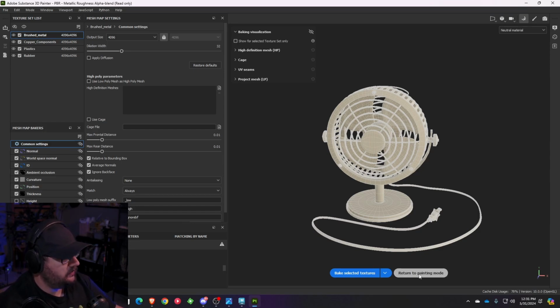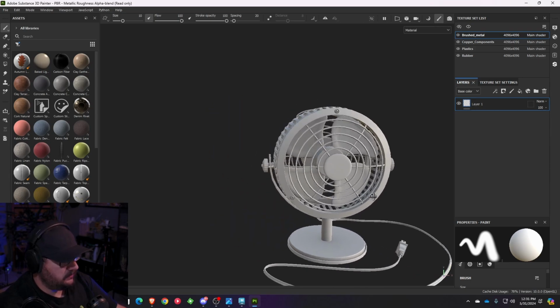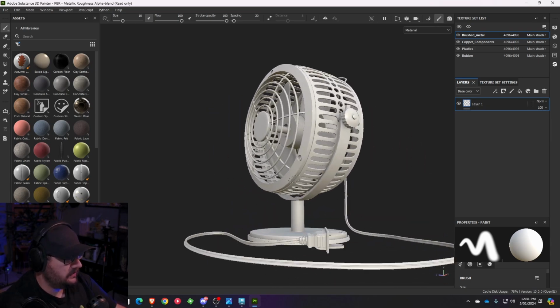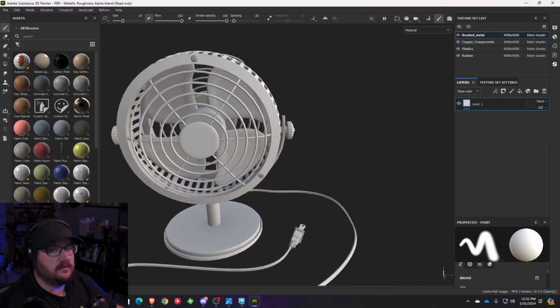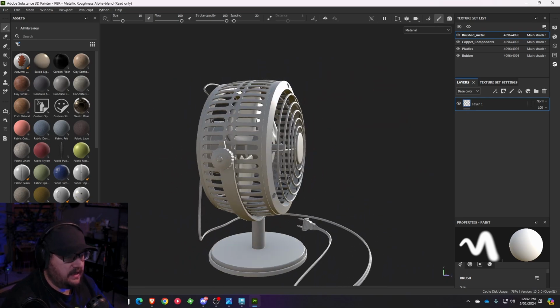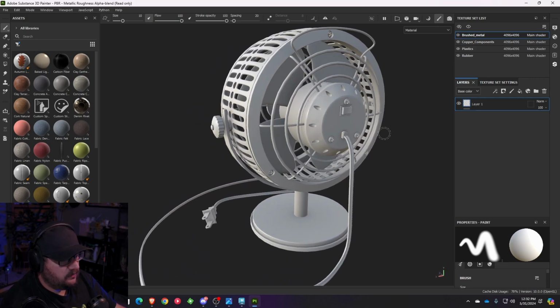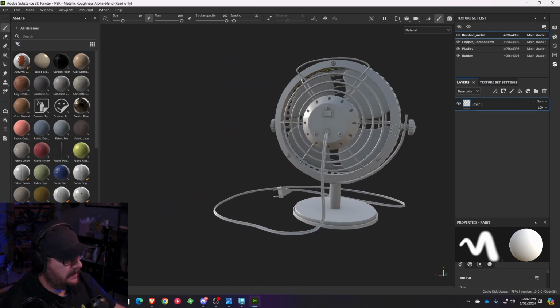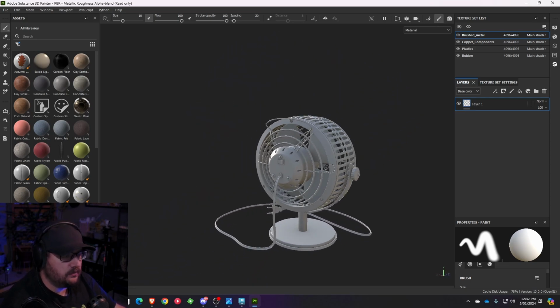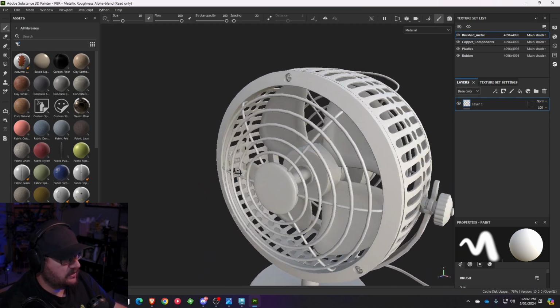Go ahead and hit return to painting mode. And you'll notice your model looks a lot nicer now. Things like shadows and ambient occlusions are actually playing into the scene now. This way you can identify, hey, my bake worked. I like to just spin around to make sure there's no errors. Sometimes you'll get weird black shadow errors. Those generally tend to be issues with your UV layout. So if you run into those, that may be something you need to go back and check.